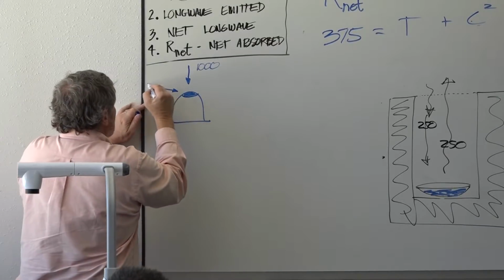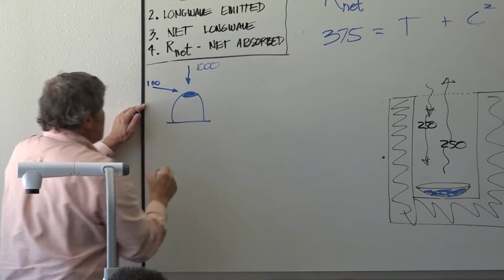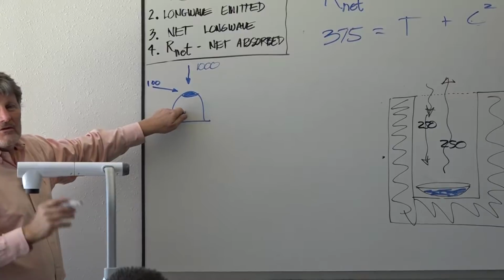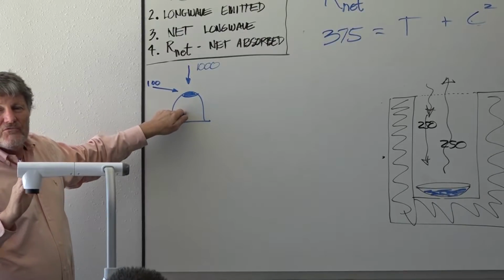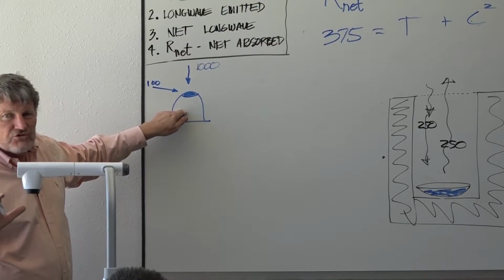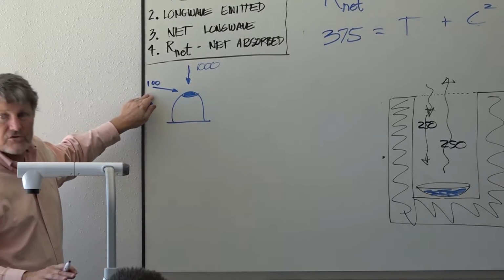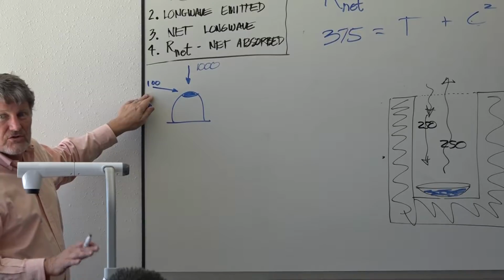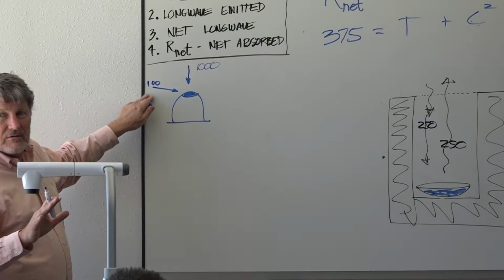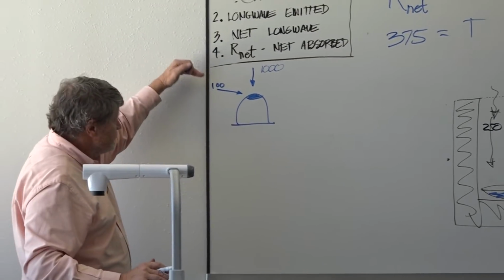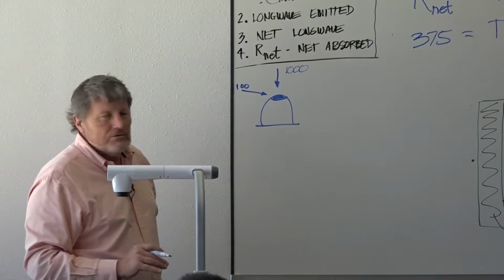So at a low angle, the correct number might be, say, 100. Now, if it reads 200, it's not cosine corrected. If it reads 50, it's also not cosine corrected. It has to be the right ratio of tilted radiation.